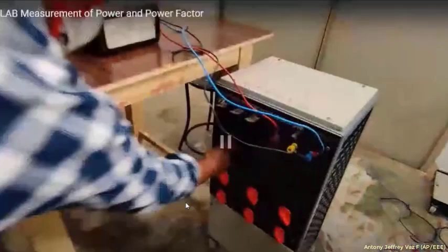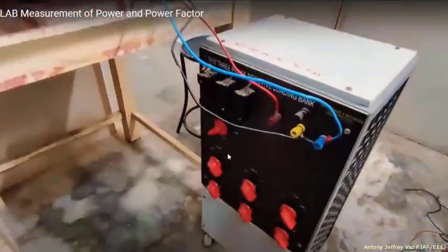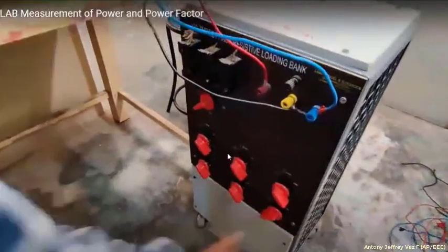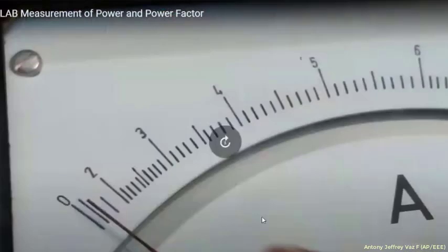Now we are going to turn on the load. You see, this is the main switch for the resistive load. First, you need to turn on the main switch over here. After turning on this, a resistance of 0.5 kilowatt is turned on. You can see the ammeter deflection of 1 ampere from 0 to 2 amperes.